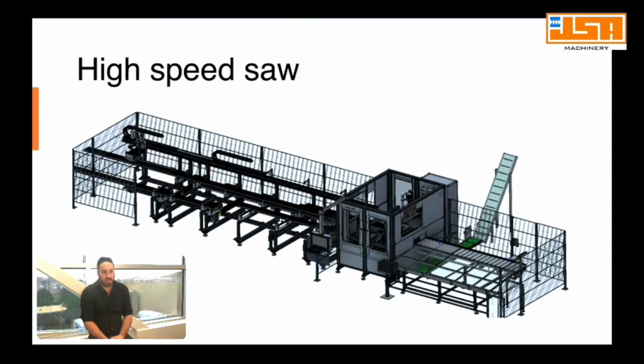So 2 different types of saw, where you're going to be cutting either 1 bar at a time, which is going to bring you to your goal of 400 squares on a shift. Or if you're cutting 2 bars at a time, you're going to be able to actually feed 2 welders or 1 double stack welder for somewhere around 800 squares in one 8-hour shift. So as I said, there's been a lot of advancement in those saw technologies. Just keep an eye on those if the saw is your bottleneck at this point.